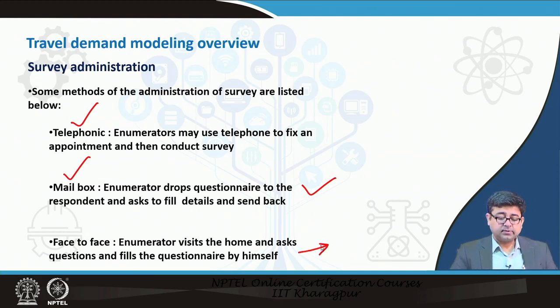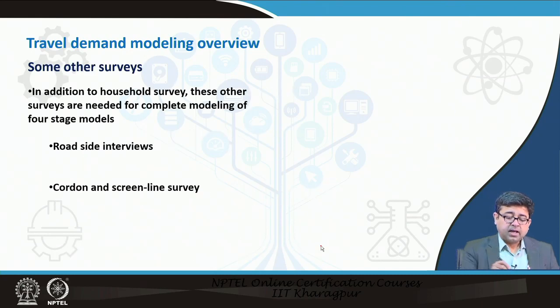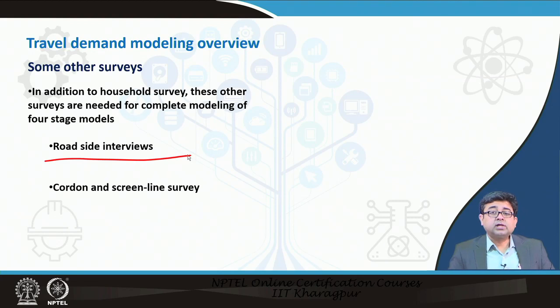Face-to-face household surveys are something that is done very often, and in some cases you also do roadside interviews, where essentially you want to know the mode choice behavior, that is, what mode people use for a particular trip. It is sometimes advisable to catch people on their way to a particular destination, so that they remember exactly what trip and which mode they are using. Many times you would see people conducting surveys at bus stops or rail stations to understand your travel behavior or mode choice behavior.